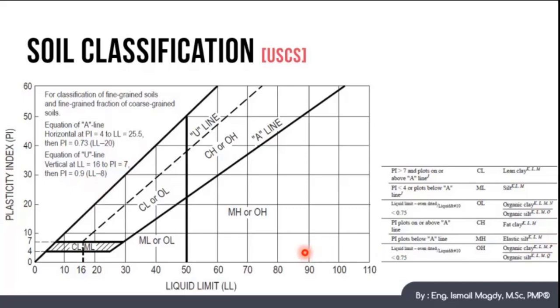For any given soil, we need to calculate the plasticity index of the soil and compare it with the plasticity index calculated from the lines to accurately identify the soil group. I know that this might seem confusing right now, but you are going to realize how simple it is once we start solving an example. So let's check it now.